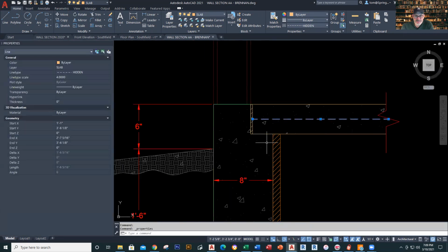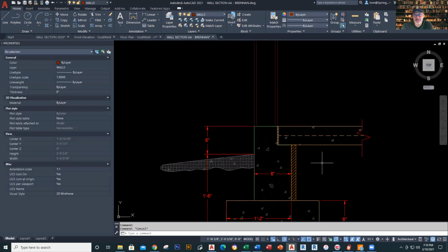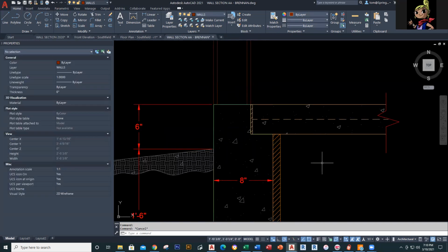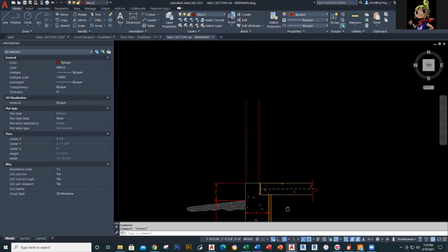Once you've got that, you see I was able to override this to line type. And if I change the line type scale here, this is what makes it larger or smaller. I'm going to make it 8, and watch what happens. I type in 8 and hit enter, and see how the spacing got larger. And if I make it 20, it gets even larger. And if I make it 1, watch what happens. It gets really tiny. Okay, mine was at 1. Yeah, your line type scale will impact how large that appears. All right, thank you. Very good, good question.